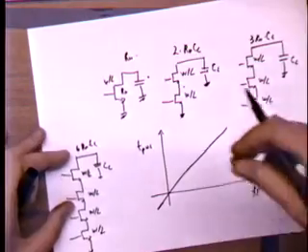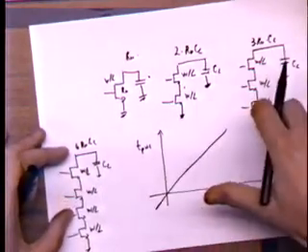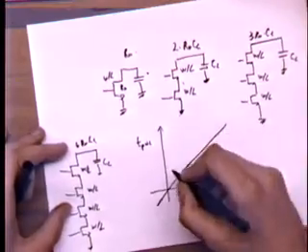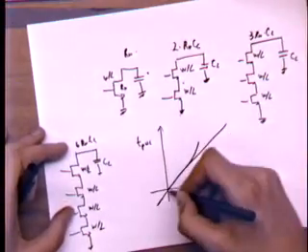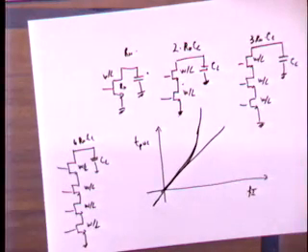However, if you try and do this exercise and you simulate in SPICE, you don't find a linear function. You find something that looks like it goes a lot faster. It's more a quadratic function. Okay? So why is that? The reason is these parasitic capacitors that you add.